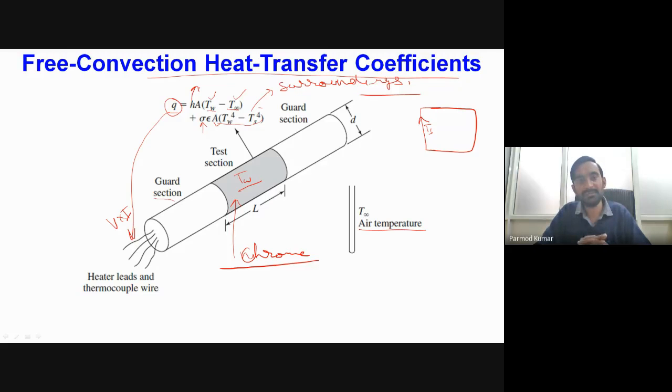Okay. So from this discussion, you might have observed that we do not have any standard measurement device or instrument for determining the value of the convective heat transfer coefficient. Rather, depending upon the physical situation where we have to do the measurements, we are employing our general heat transfer laws, and with the help of these laws we are developing some indigenous measurement arrangements for obtaining the corresponding value of the convective heat transfer coefficient.